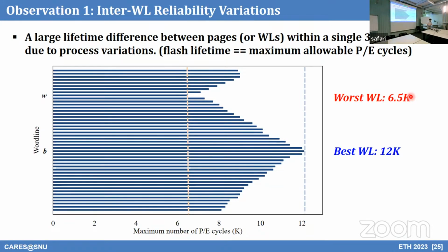Okay. So from this idea, what you can see is that what decides the lifetime of this block is this worst word line. So in SSD, because data reliability is very important, the design is more or less based on the worst case. But as you all know, if we want to optimize, the design should support the common case.